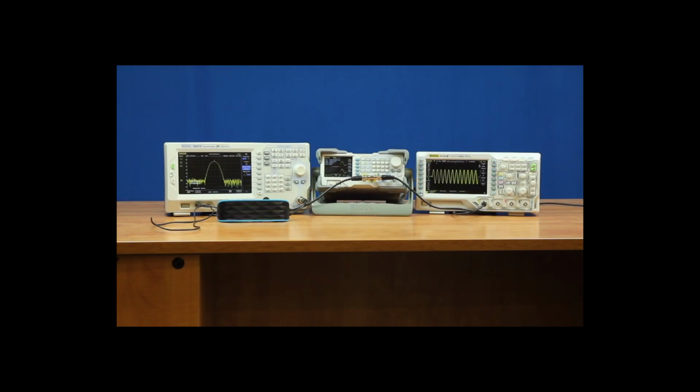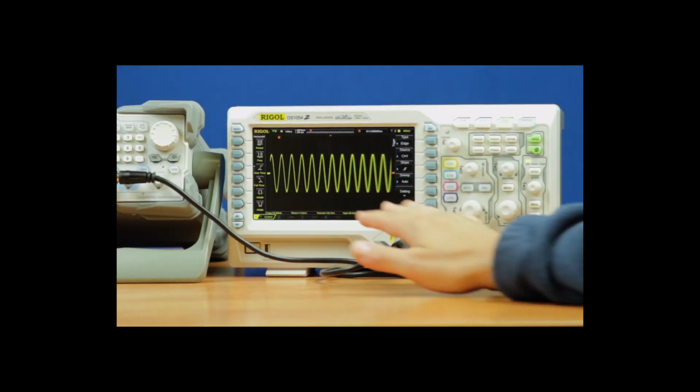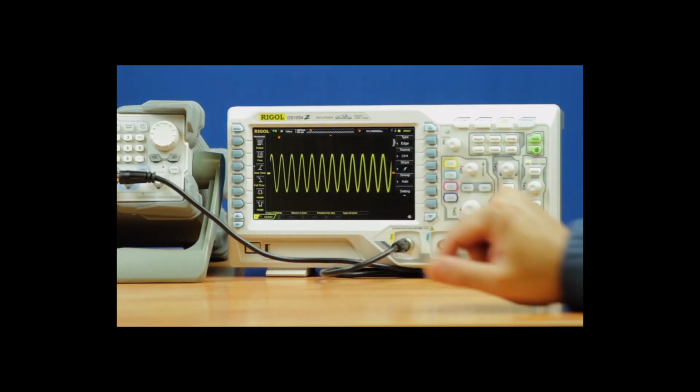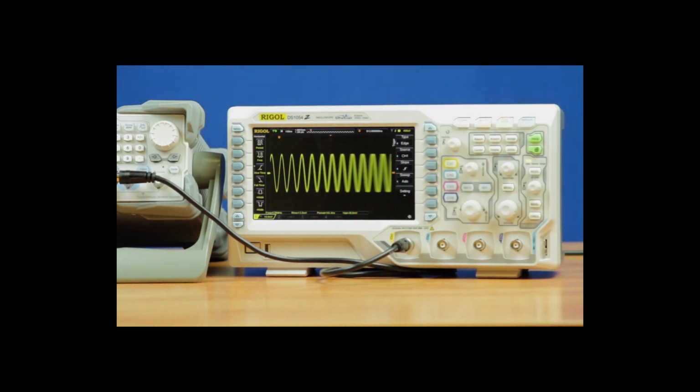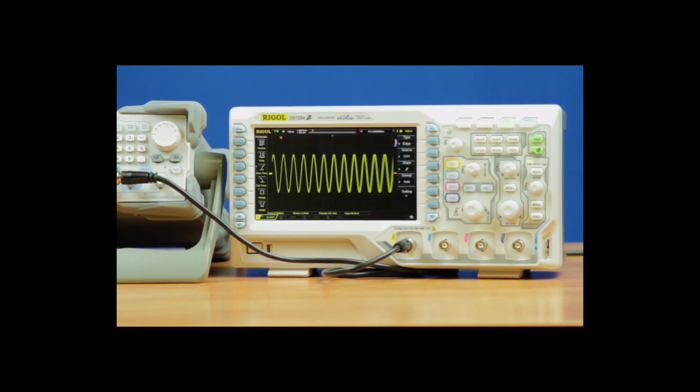So now I've changed the setups to load the FM external setup files. So now we're loading the same audio, externally modulated, this time as frequency. On the scope, I've moved the trigger over to the left side, so we can see how the frequency changes over time. So you can see the more alterations as you get about 5 or 10 cycles, you can start to see the modulations. But again, the spectrum analyzer can pick those up more clearly.